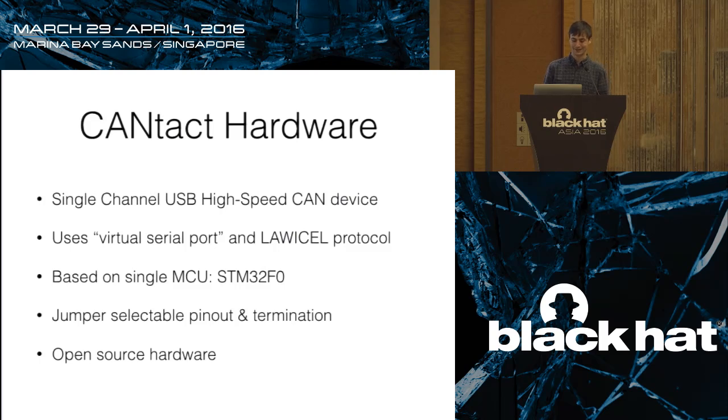And the hardware, it's a single-channel USB high-speed CAN device. USB in one end, CAN in the other end, it gives you a network interface. It uses the virtual serial port USB profile, which, because it's over USB, actually allows you to do quite high-speed transfers. You can do 64-byte endpoint transfers and do it at speeds quite a bit higher than you'd expect with RS-232. And it uses this LAWICEL protocol.